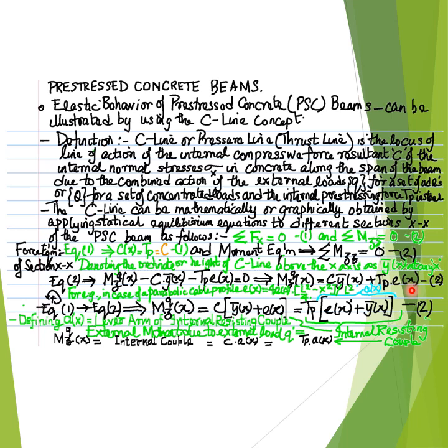The eccentricity function denoted as E with the argument x, representing the eccentricity of the pre-stressing cable or pre-stressing tendon at any general location x along the x-axis or x coordinates, is considered positive by sign convention when the eccentricity E at the general location x is below the neutral axis for the pre-stressing cable or the pre-stressing tendon.